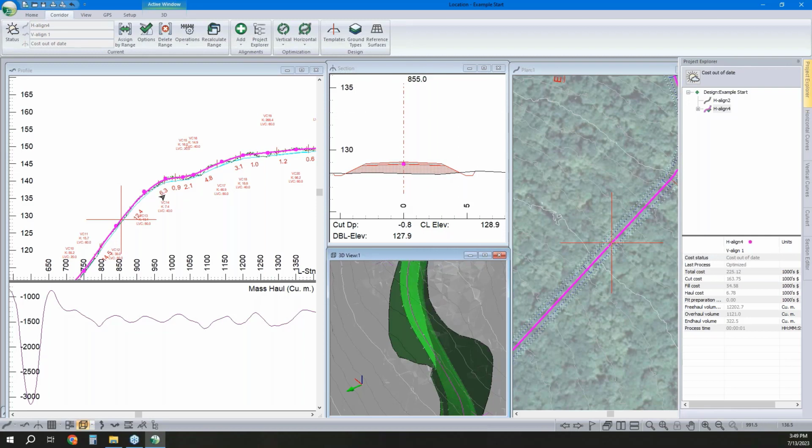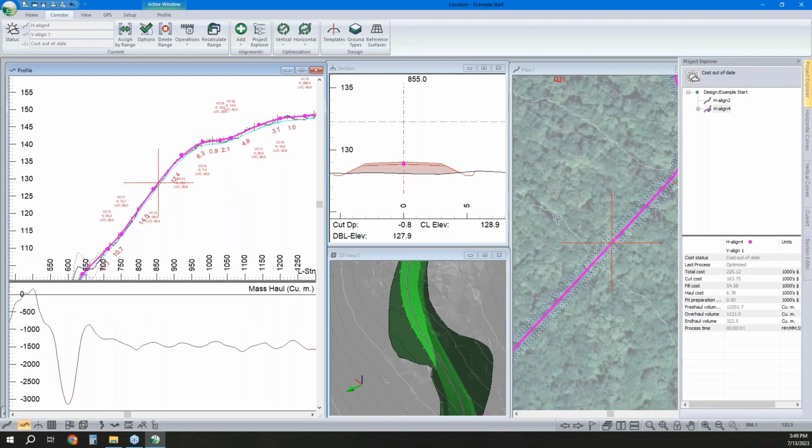So on steeper grades, you have a longer flow path of your water on the road top, but it's moving away and getting pushed off. Now the flip side to that is if you have a subtle crown and you're on something that is 0 or close to 0, which often becomes apparent on the crests of hills and the sags and valleys, you get a lot of potholes.